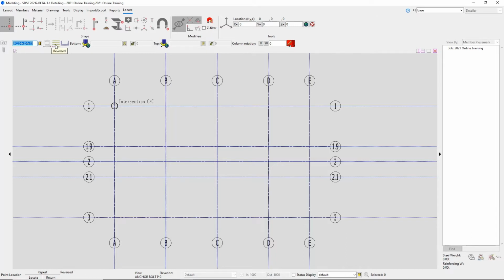If you want the section reversed, and then this third one is if you would want to choose double or single material. In this case, our section size doesn't allow us to specify any of those options, so we'll just move on. The next is going to be dealing with our bottom end settings for this column.